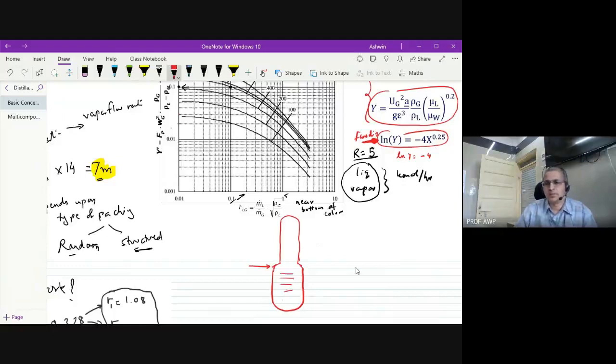Here the diameter is different because the liquid and vapor flow rates are different. But if the difference is not large, if column diameters are not large, fabrication issues are there in fabricating such columns. So you might want to just fabricate the entire column with a bigger diameter, whichever you calculated from the bottom of the column calculations. Do you agree with that?